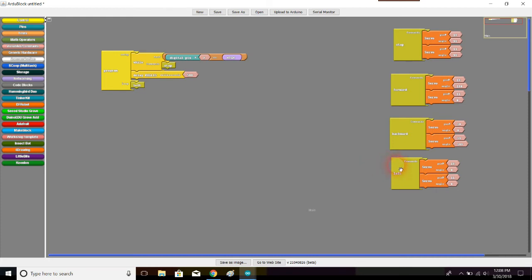So, hopefully with this, you can get each of your students to define, I spelled that correctly, to define and test each of their subroutines until they at least have these five: stop, forwards, backwards, left, and right. You can also have them create a blink subroutine that blinks the LED. You can have them do half speed, backwards and forwards subroutines as well. But they should at least be able to, if given these two, find the other three.